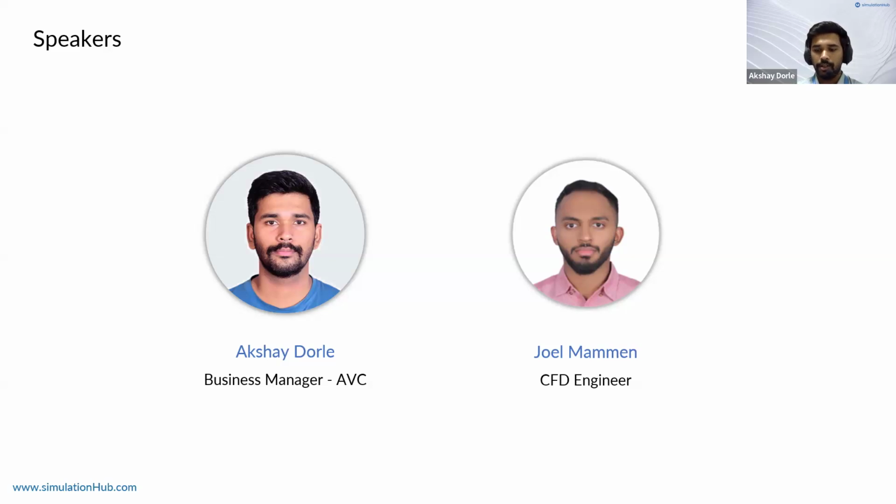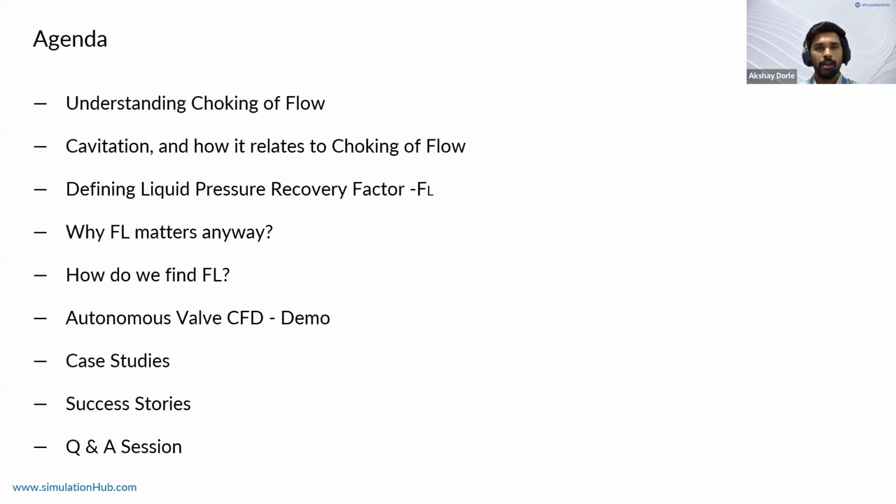So let's jump into today's agenda. We'll try to understand what is choking of flow. We'll then see how it relates to cavitation. Then we'll define the liquid pressure recovery factor. Then we'll see why exactly FL matters and how to find FL.